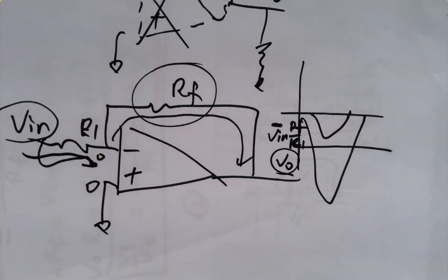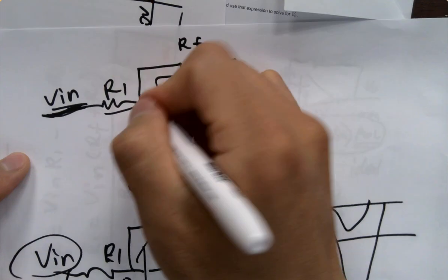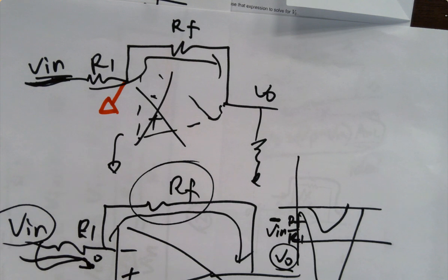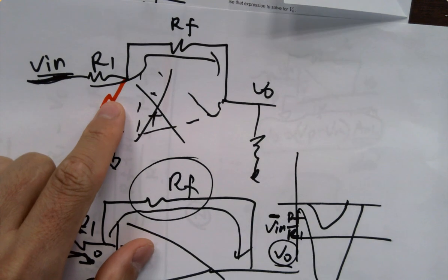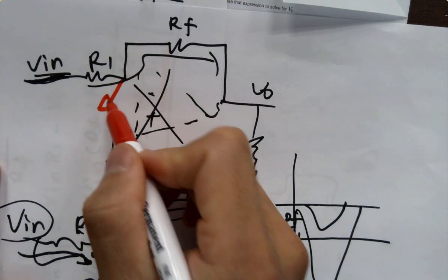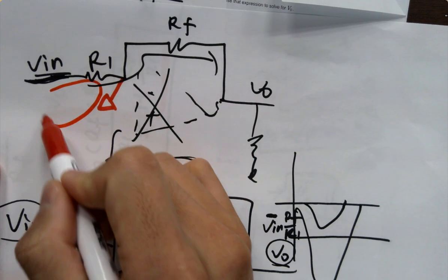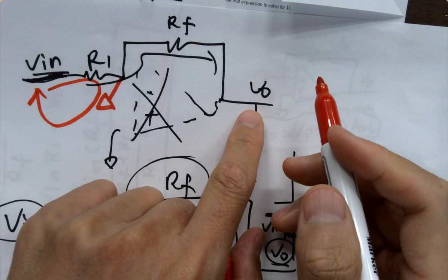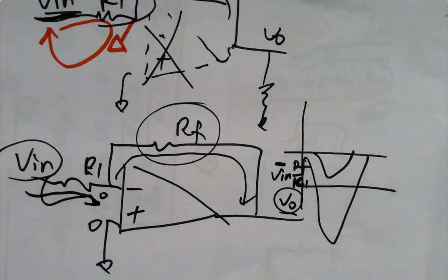Then we brought another question. Why not just simply, in this circuit, ground here, just ground it? Why do we have to create a virtual ground instead of just grounding it? Yeah, if you really physically ground it, that's the real physical ground. What's going to happen is it's going to circle the current to itself instead of going to V out. Virtual ground is not a real ground. It's just 0 volts, but it's not physically wired to the cathode of the battery. Does that make sense? That's a fundamental value of the op-amp. Right? That's how a signal is getting amplified.